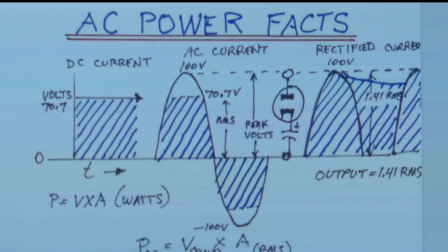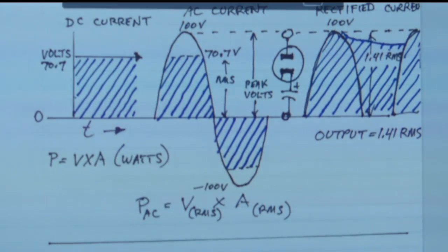So you square the value you take, then you average the value over all of the samples you've taken. That's the mean part. If you've taken 1,000 samples, up here and down this wave, that's the mean or the average, the number of samples you've taken. You divide that into the squared values, and then you take the square root of that. So you've got that collection of values, you take the square root of it, and you'll come out with the RMS value.